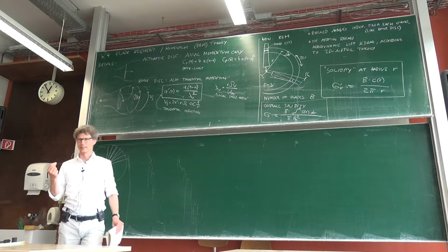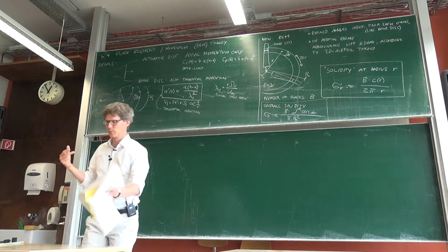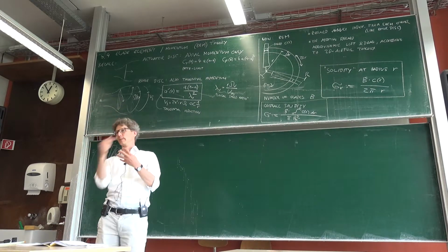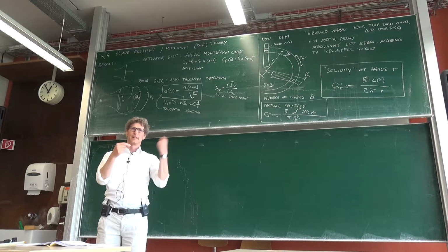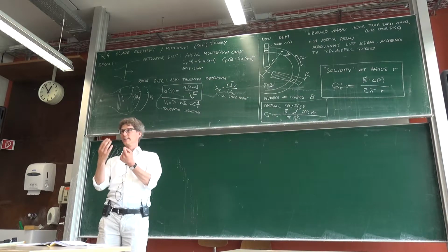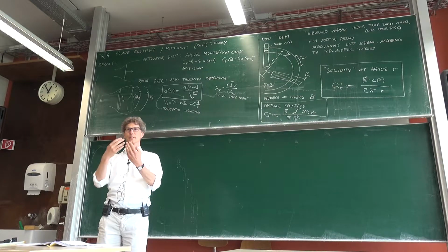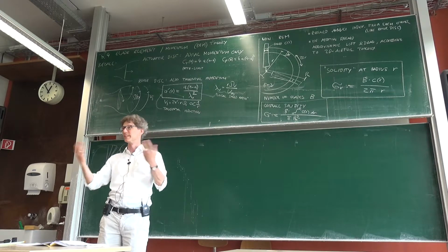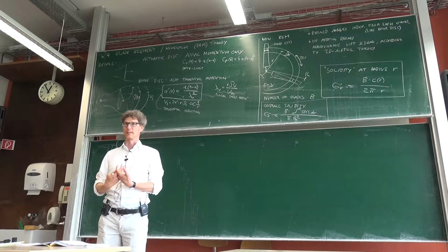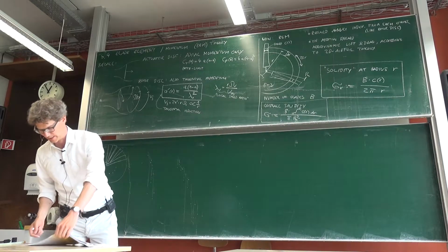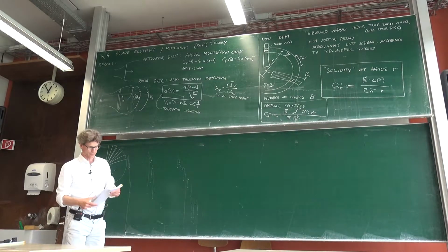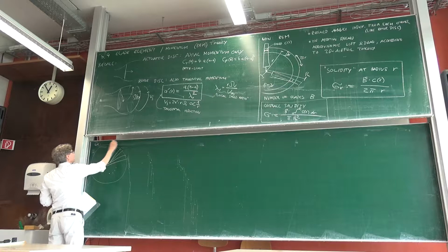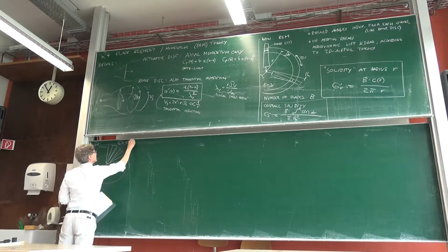But the main difficulty, as I said, is that we want to bring two worlds together, namely the world of an airfoil which just feels a force because there is wind, right? And the other thing is the wind that gets slowed down or changed because there is a force. These two things together mean that there is a wind that depends on the airfoil, and the airfoil depends on the wind, and they couple with each other. And that's what makes blade element momentum theory interesting, but also complicated. So this was an example, sigma 100%.